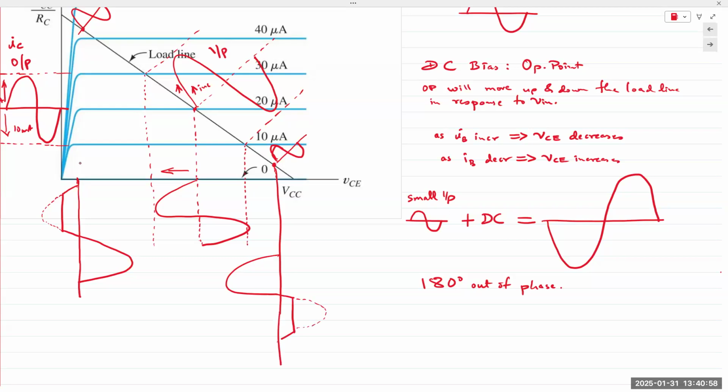In both cases, the result is distortion, which is what you would notice in an audio system. You would notice this as tearing sounds coming from a speaker. You have an audio system, you turn the volume up too high, now you're forcing too much voltage and current to go through the system, and perhaps your speaker also cannot handle it, and so that's how it sounds. It sounds as tearing noises coming from your speakers. So that's a distortion and clipping that occurs due to a large input signal or due to a poorly designed biasing circuit.